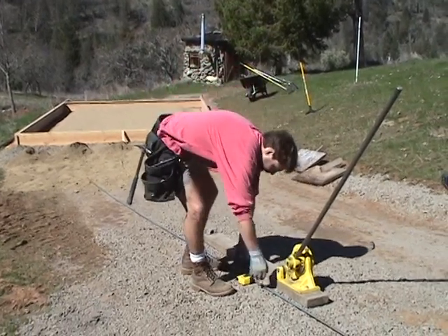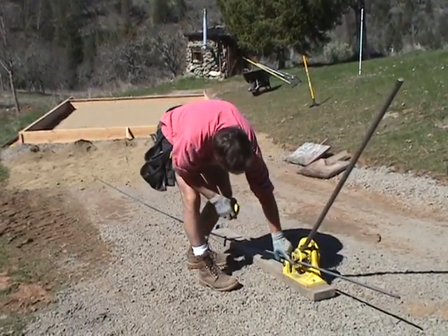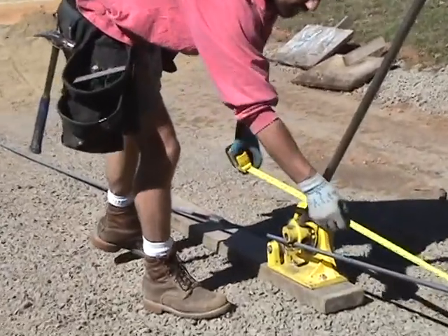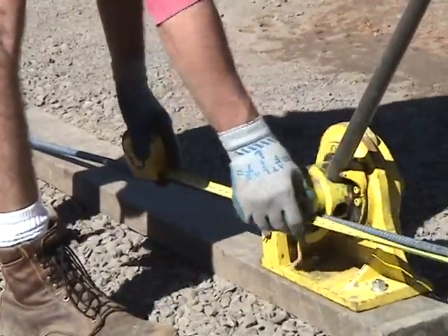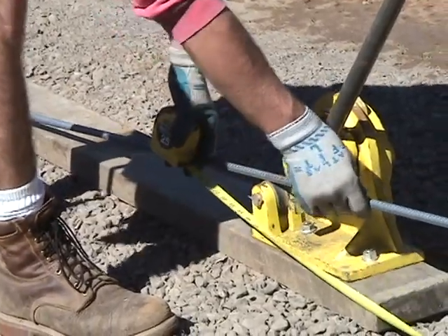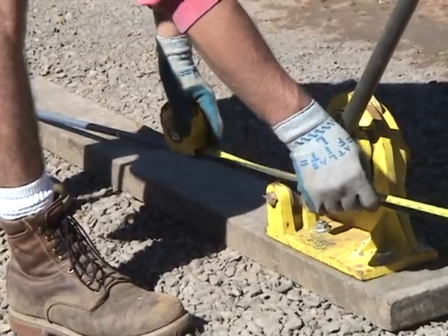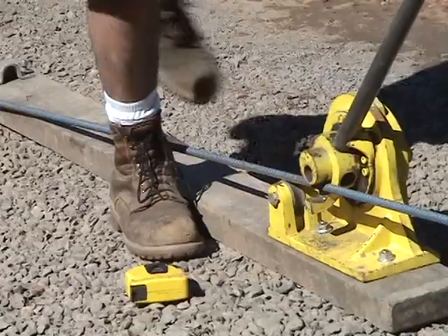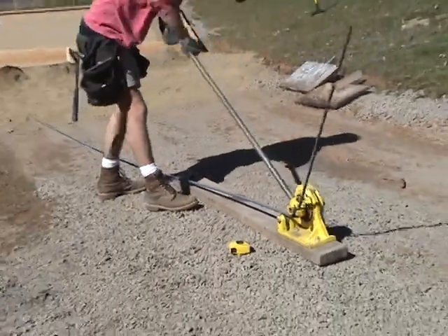We'll place the rebar for bending on the wheel and underneath this, or I'm sorry, above this cuff. It can be pretty rough with rebar to where you need to measure it. I'm going to be pretty close here, and right about there. The measured area goes right underneath in the middle there, because that's where the bend is going to take place. Once it's in place, you grab the pole, just lever it right back.